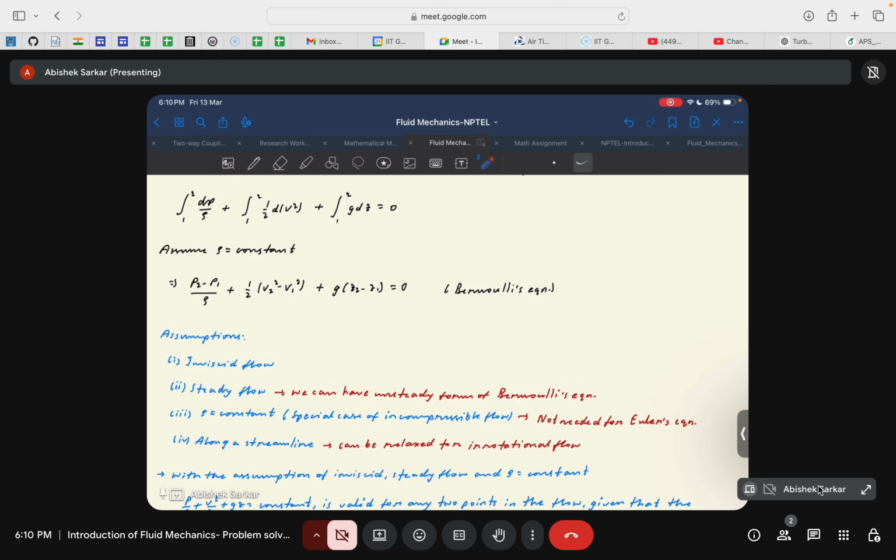primarily because the velocity on the upper surface of the airfoil is higher, because of the curvature, than the velocity at the lower surface. Because of Bernoulli's principle, we can say the pressure below the airfoil surface will be higher than the pressure on the upper surface, which will give us the required lift. But now we know that for interpretation purposes it's good, and it can be applicable in generally many cases. But for proper, accurate analysis, you now know that this is not the case.